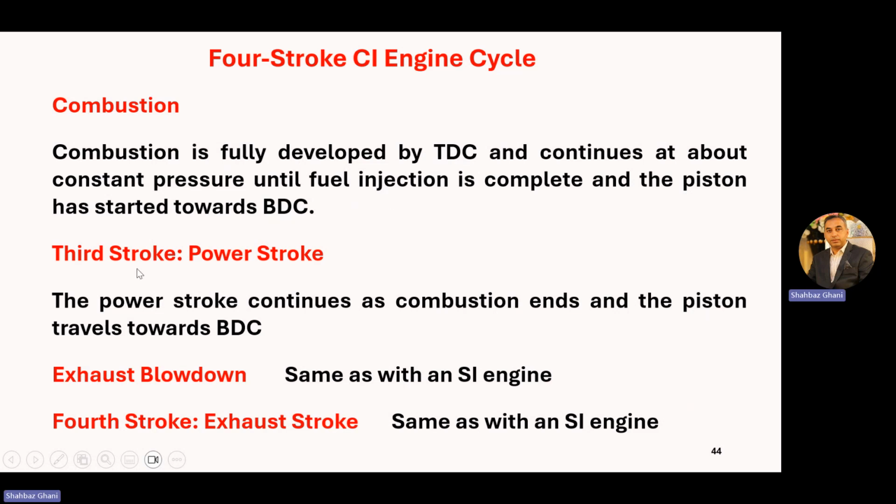Okay. Now, the third stroke, the power stroke. The power stroke continues as the combustion ends and the piston travels towards BDC. Exhaust blowdown, same as with an SI engine, same phenomenon. Fourth stroke, same as with the SI engine. Your exhaust valves open and exhaust gases go out.